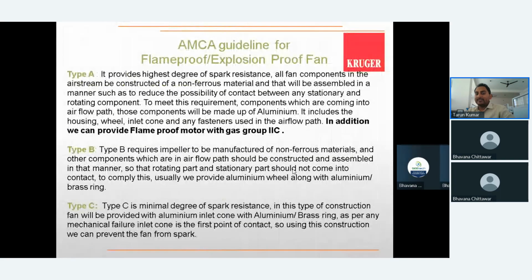Here AMCA has given a guideline. AMCA, probably everyone is aware, is the body which certifies the fan for whatever air we are claiming. Suppose we claim this fan is designed for 50,000 CFM or 60,000 CFM. They will take the fan into their lab and certify that this fan can deliver this much CFM and static pressure. They will check and verify, and give the certificate for every fan manufacturer. It is very mandatory. At the same time, ATEX is again a third party body which will certify that the fan can be used for flame proof application.